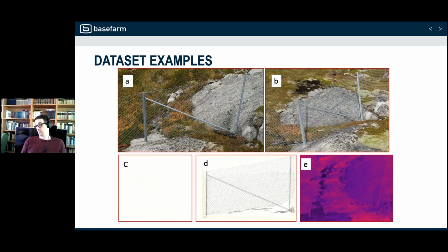What you can see on picture D is the high resolution LiDAR scanning that was done from the ground with a stationary LiDAR. What I have to say about this laser scanning is that it's millimeter precision, and it results in really high data density and a high amount of data. The data amount was 22 gigabytes and 900 million data points for the scanning of this airport.